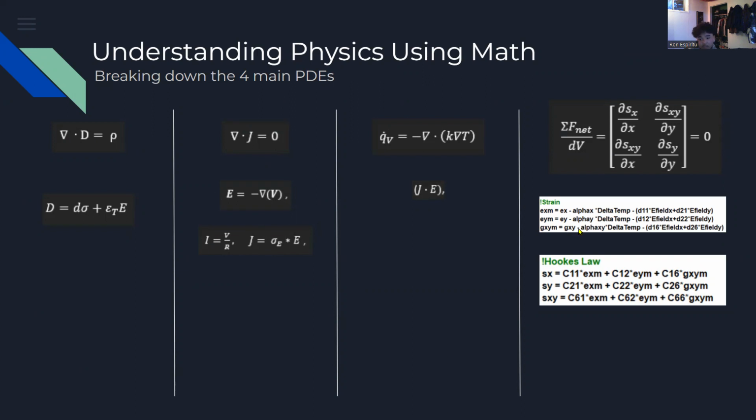The final equation comes from the stress form of Newton's second law. In setting this partial differential to 0, the x and the y displacement that puts the system into equilibrium is calculated. It's built by calculating the piezoelectric strain, which is the D matrix multiplied by the electric field, and the thermal strain, which is the thermal coefficient multiplied by the change in temperature. This is related back to the equation by multiplying these strains by the material's stiffness.